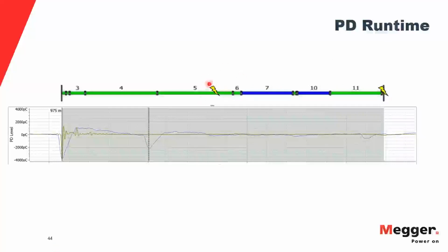The other phenomenon we have is called dispersion. Again, it's related to the length of the cable. As the cable length increases, the pulse gets wider and lower. Kind of similar to a TDR if you've used those. That's because the cable filters out high frequencies. So we see here this nice, sharp, tall pulse, it has a lot of high frequency components in it. As that pulse travels down the line, it loses more and more of those high frequencies. So we no longer have that nice sharp edge, and we wind up with this lower and wider pulse.